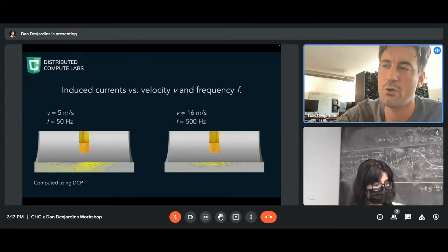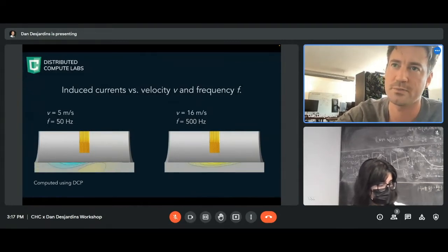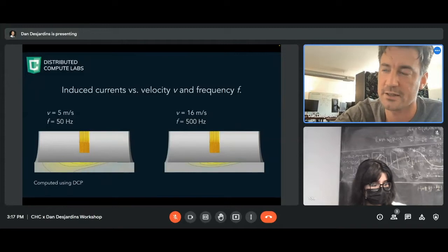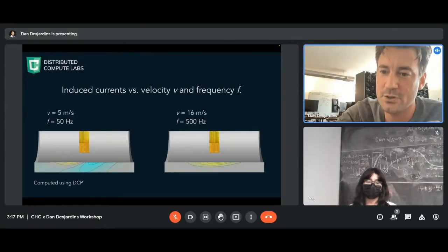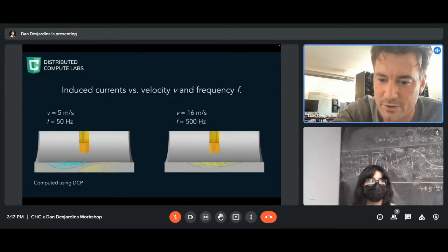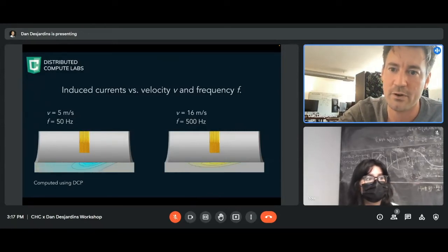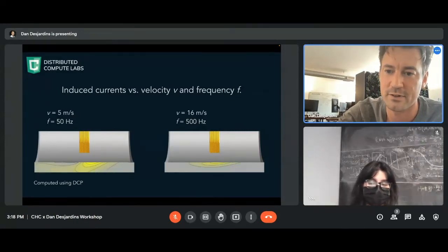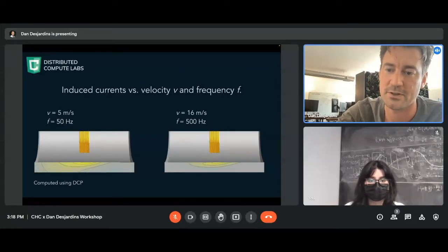Think about that. The coil induces a cushion of currents behind it, and then the coil reverses its polarity because it's at 500 hertz, 500 times per second. So the coil creates a cushion of currents, and then it reverses its polarity, and then it pushes on the cushion of currents that's lagging behind it. And then it induces the opposite polarity of currents, but then it reverses its own polarity again. So it continuously generates a wave of currents behind it and then pushes on that wave. Now, of course, like I said, it's not stealing energy here. The currents that it's setting up in the metal, or the power being dissipated by those currents, are coming from the coil itself. So you're not getting anything free here.